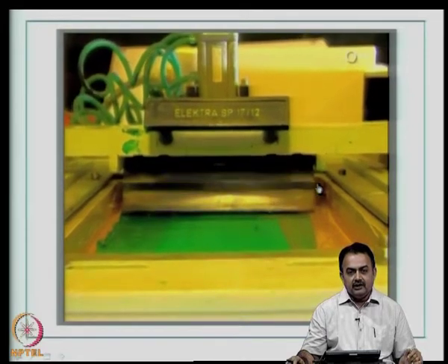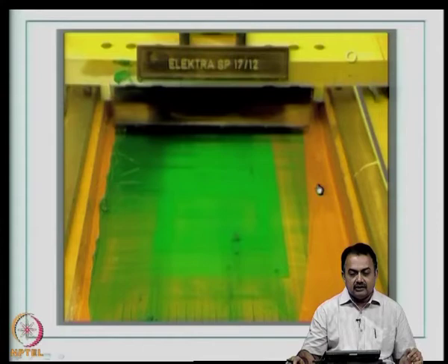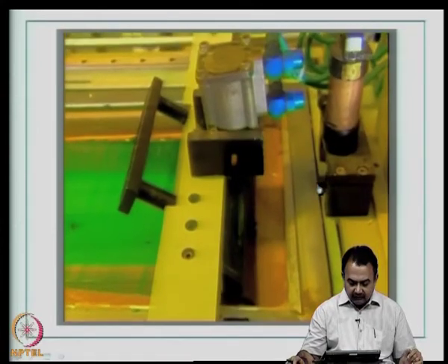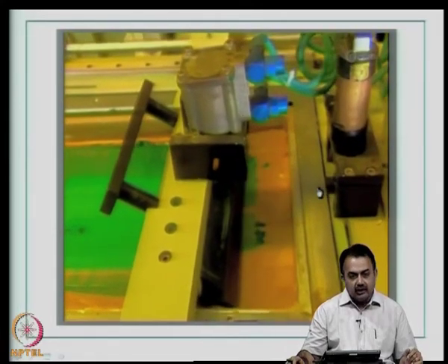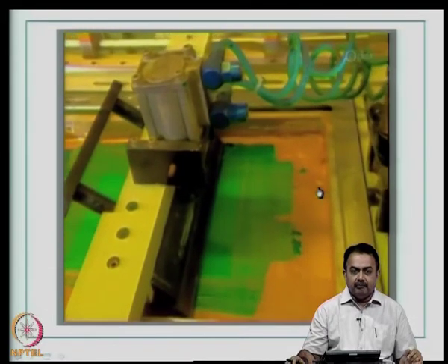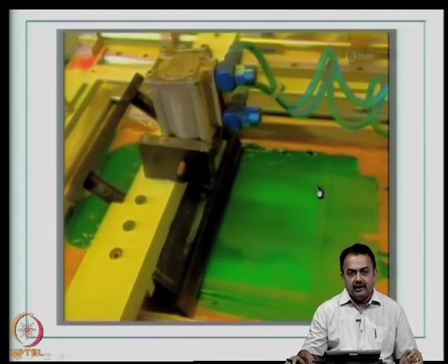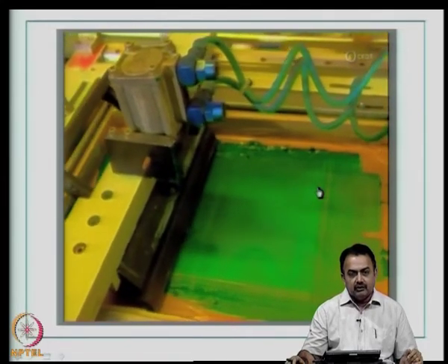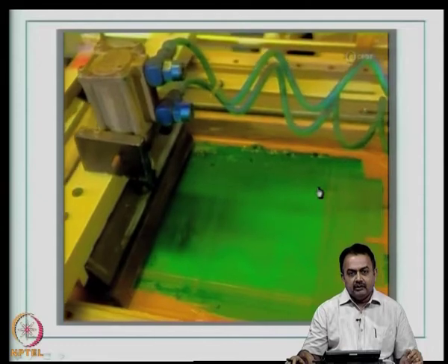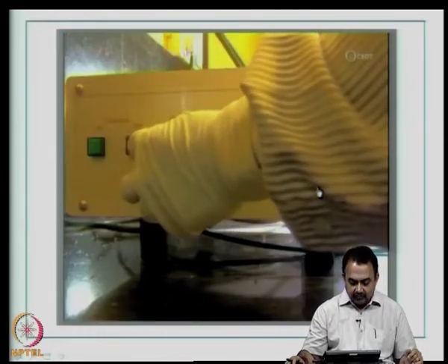Now, the ink is dragged or pushed through the mesh openings on the stencil onto the surface of the PCB. If required, you can also do a second motion of the squeegee blade in the reverse direction to the original starting point and then finish the process.